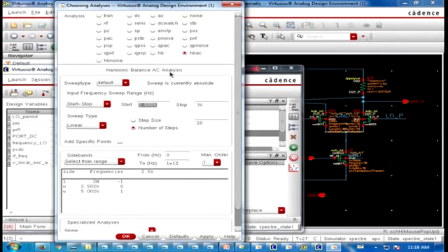You linearize any nonlinear circuit in a small signal domain, and then you apply whatever input voltage, like 1 volt, so that you can get the gain, or the output as a ratio of output by input. But this is a nonlinear circuit, so you have to go for a nonlinear AC analysis, which is called harmonic balance AC analysis, because there are 2 inputs and 1 output.